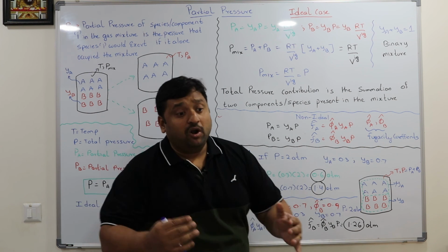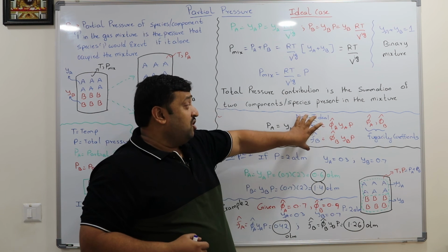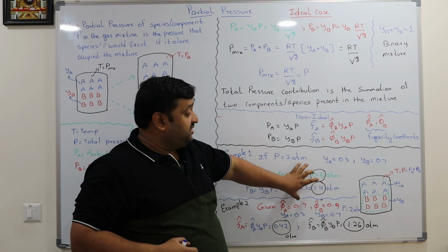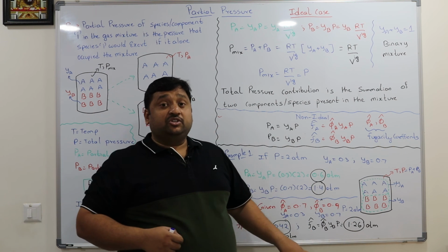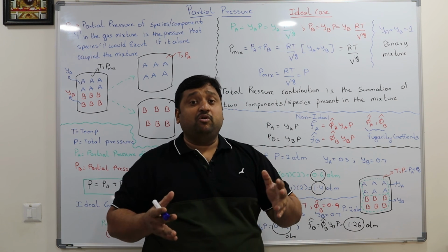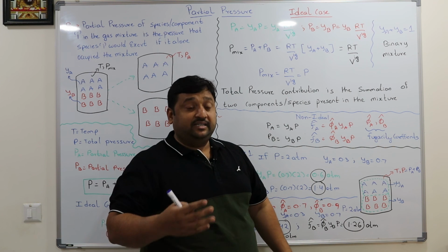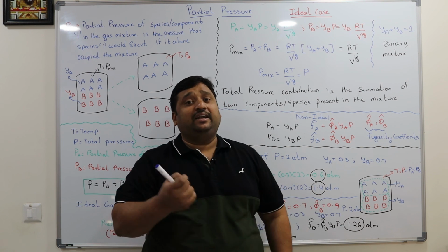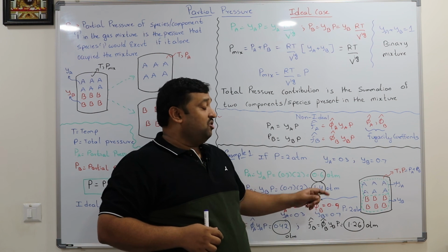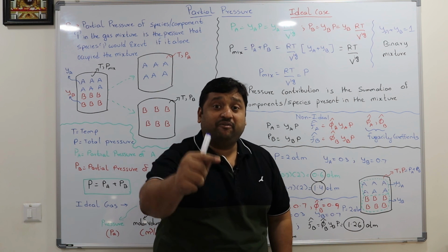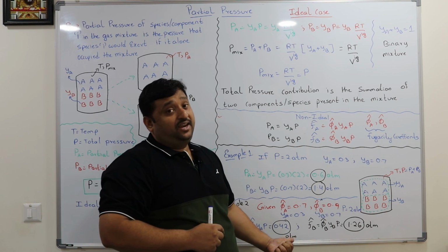That is why you always have to design a separator or reactor not based on ideal numbers, but based on the real numbers. So here the chemical engineer has to apply some sense, because if you design the reactors based on these ideal numbers, you won't get the purity or separation you expected, because you have designed based on idealistic scenarios. Always design things based on the non-idealistic scenarios.